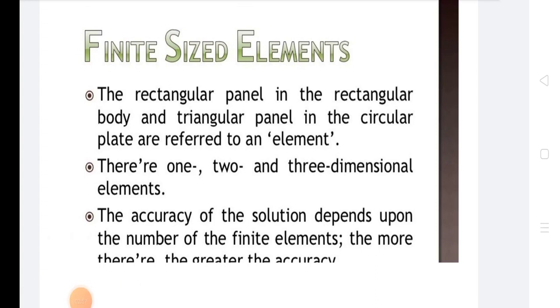or forces: the internal forces are introduced through the concept of body forces and traction forces in addition to point forces. Body forces are those which act on every particle of the body, that is over the entire volume of the body, and are specified in terms of per unit mass or per unit volume of the body. For example, magnetic forces and gravitational forces are distributed body forces.